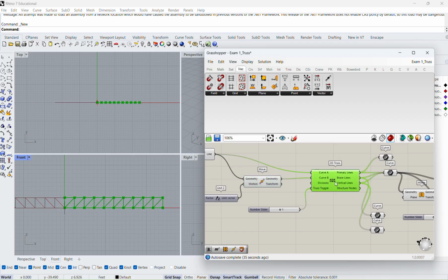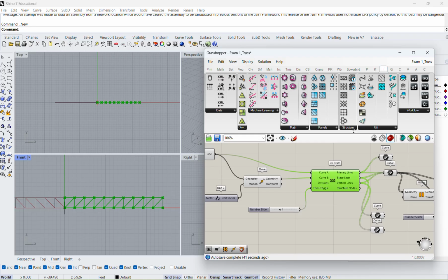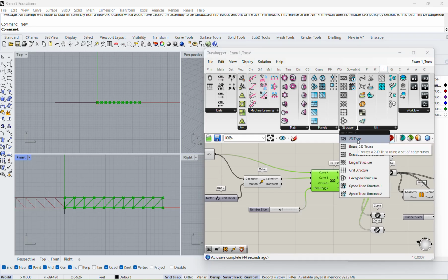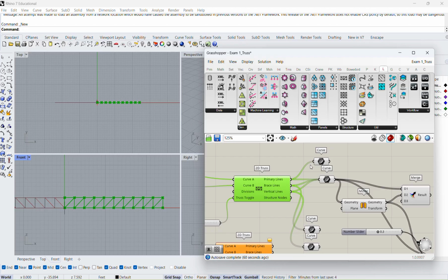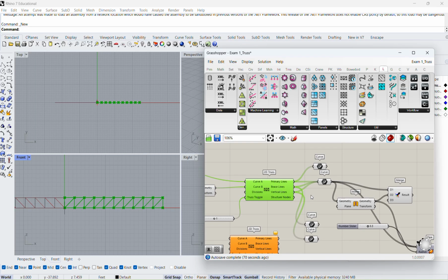So now this component is a Lunchbox component for the truss. You could see if you install it, there is the truss component. If you click this, you see that these components drop. You need to define basically the line curve, bottom curve, and top curve. With this input and truss type 1, 2, 3, I just keep the 1, and it forms the truss line. So basically after this, we complete this truss geometry set.